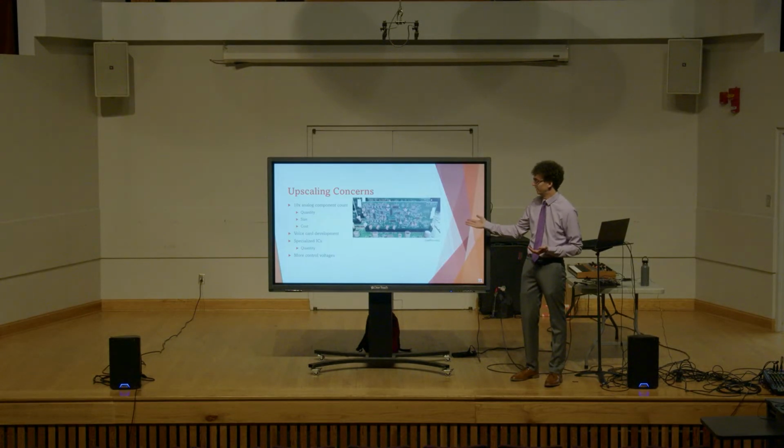And it's shown here as a very, very compact and well thought out voice card, which implements a very interesting method of installation, which is PCIe, which you see a lot in computers for installing sticks of RAM. You establish contact pads on one end of your PCB, which will slot into a slot on your master control board, and then provide your connections that way. So you're not running X number of cables between X number of boards and having a big old mess inside of your machine.